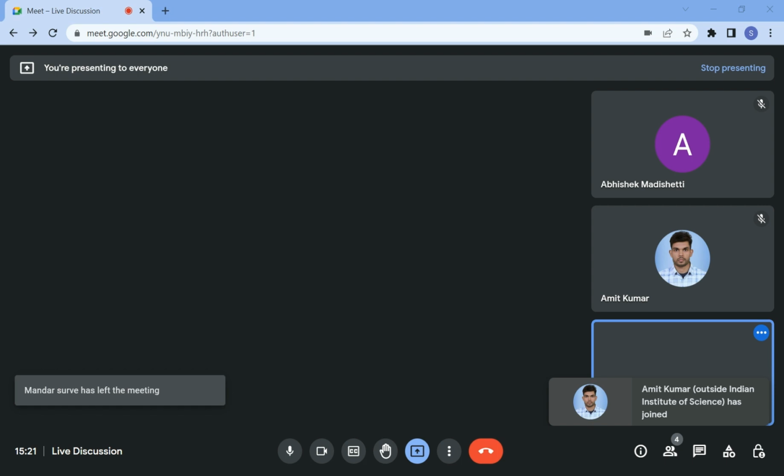So you keep the compass here, and then you put an arc that has the length of this projection, which is L cos 30. You mark it here or here, wherever. So that will be the projection of your line, and this should actually be in line. That is how the construction goes. You need to get the locus of point B once in the vertical plane and once in the horizontal plane, so it's a line and a circle. One is the locus of 30 degrees, one is the locus of 45 degrees.